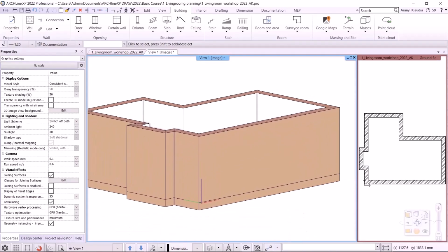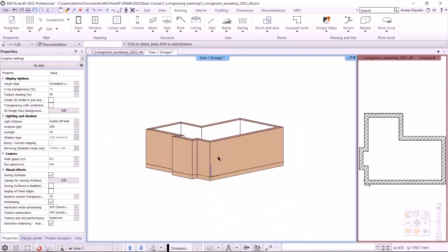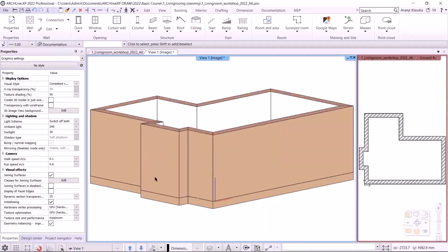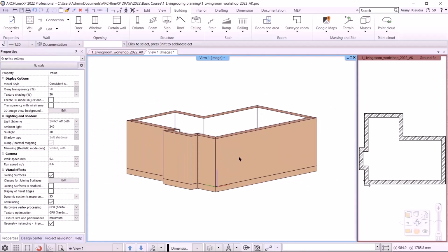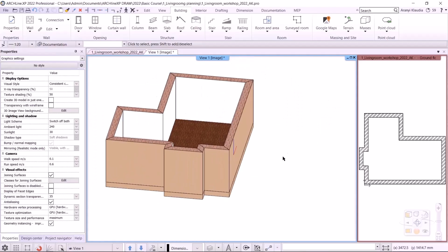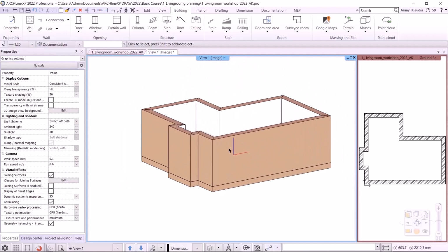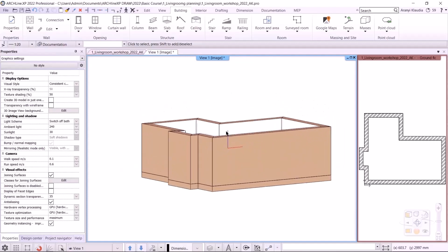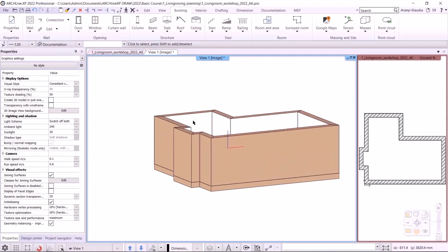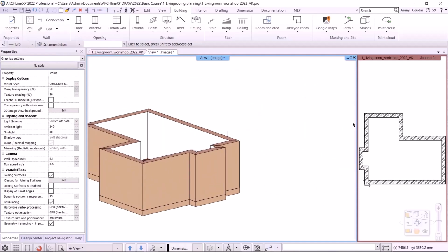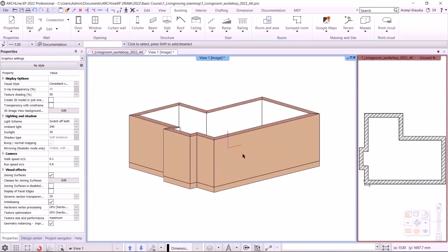I can move it by pressing the mouse scroll wheel. Double-clicking on it is the optimal zoom. If I press the right mouse button, I can rotate it. Also notice that when I am in the axisymmetric view, whichever point I press the right button at, the center of the rotation is moved there. It rotates around the point. Let's put the floor plan back on the left.